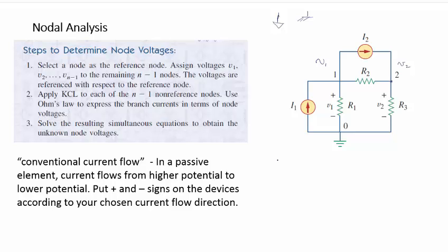That's what the textbook says, but essentially it means to establish what your current flow direction is. So if I say that current is going here, I assume V1 is greater than V2, and I put this potential higher than this potential. It's somewhat of an arbitrary assignment because you don't know until you analyze the circuit if voltage at 1 is truly higher than voltage at 2, but I have to make some assignments in order to analyze this circuit.